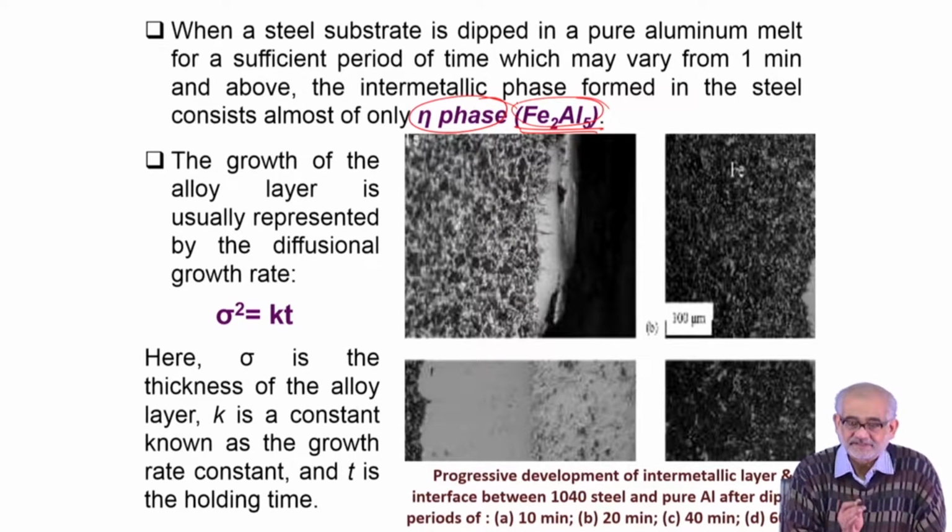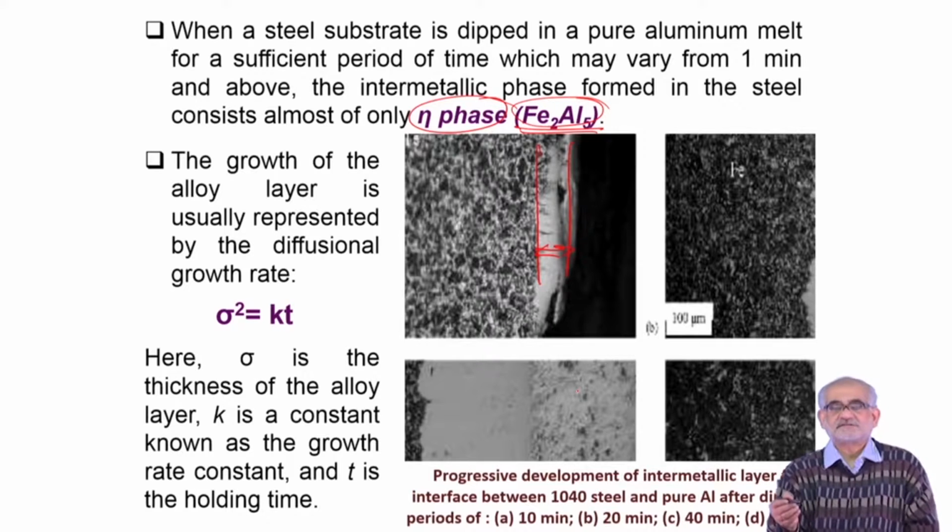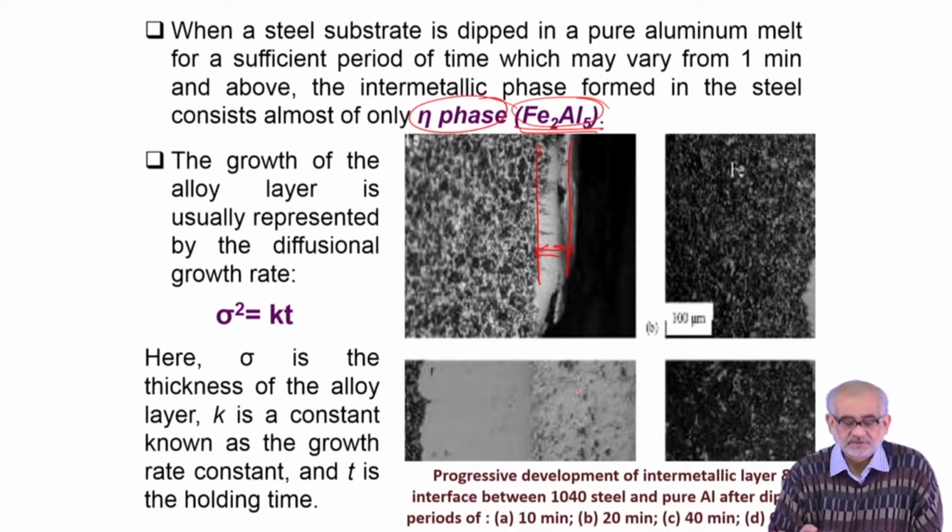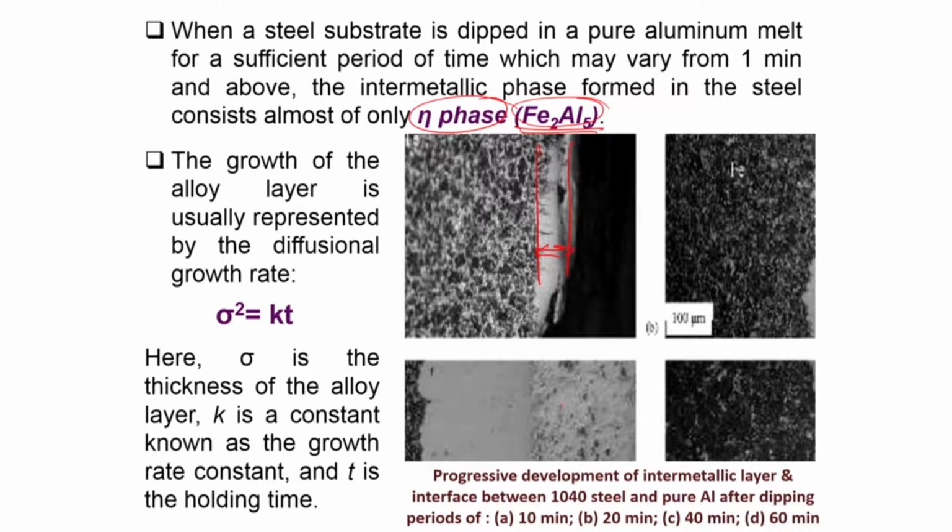So they form a barrier layer. This is the kind of barrier layer that we are talking about, and in fact this barrier layer that we form, the aluminum rich layer, will grow with time if we increase the residence time in the furnace, in the diffusion coating chamber. So the cross section actually will show us that it is not pure aluminum. It actually is an aluminum rich matrix phase with a lot of these intermetallics.